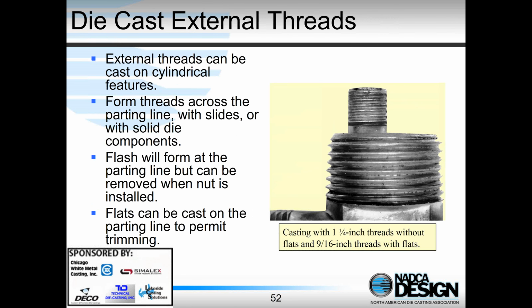So let's talk again a little bit about casting threads. I alluded to this a little bit earlier. We can cast internal threads in place. It tends to be difficult. It's basically an ejection problem, so it's not that common. So generally we tend to only do external threads.